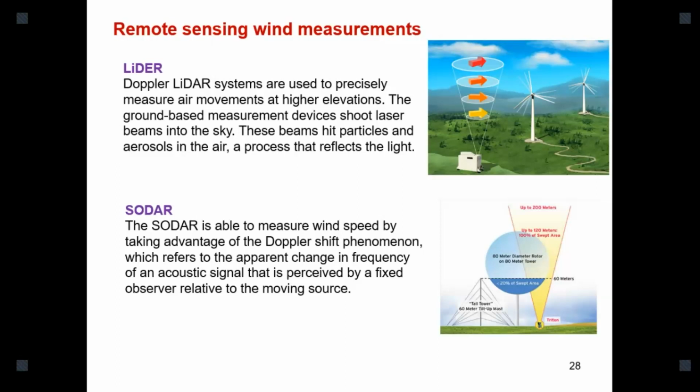You know that for energy cases, we need to build a wind mast. Maintaining a wind mast is not simple, it is costly. The wind mast may be 100 meters, because modern wind turbine heights are almost 100 meters, 80 meters, 70 meters, and in some cases 20 meters. Then we need to build a very large, very high wind mast. It is expensive. So how about remote sensing? Very simply, we can fix a LiDAR or SODAR on the ground level and take measurements.